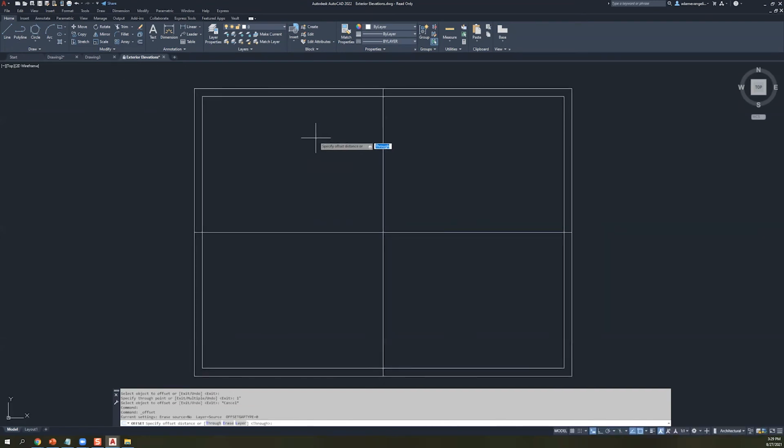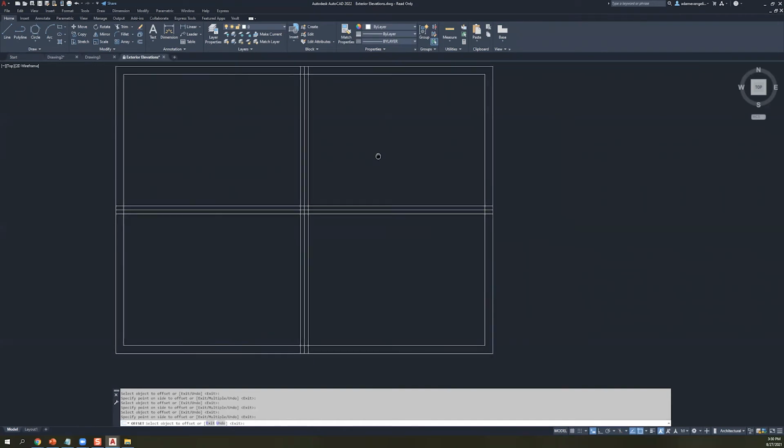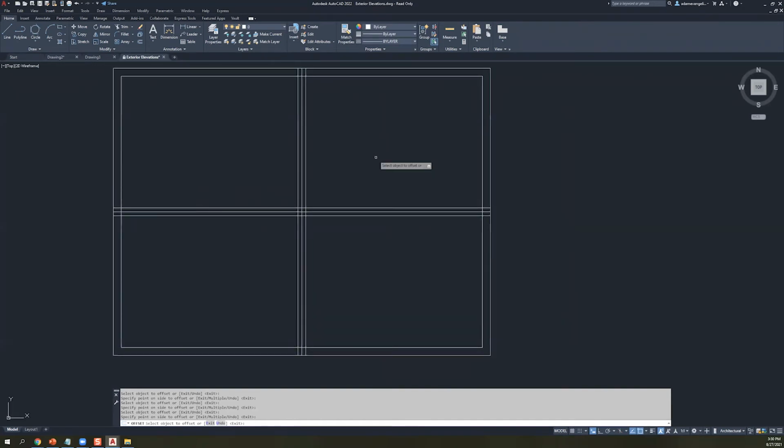I want to do the same thing, and this time what I'm going to do is start the offset command. I'm going to specify 1/2 inch specifically, so 0.5 inches, because I'm going to select this object, push it out 1, select this object, push it out 2, so that this is still symmetric around their centers over here, right? And once I have something like this, I mean, this looks pretty sick, this looks pretty dope. But I do have some lines to clean up.